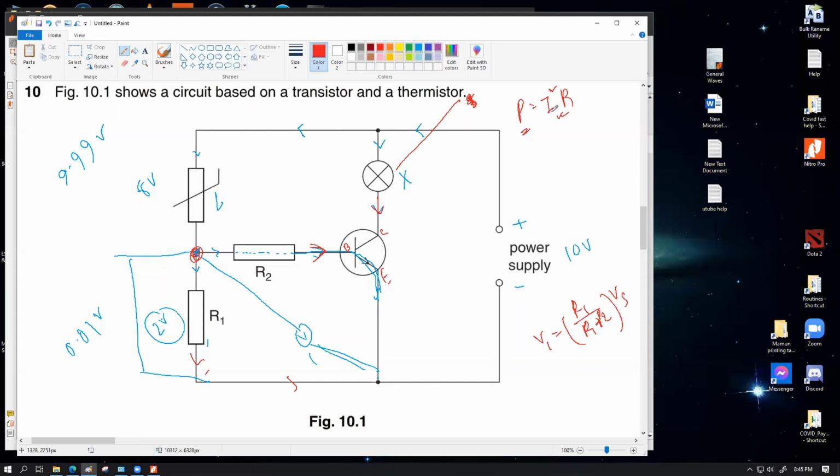So let's say you buy one of those bulbs and take a 1.5 volt battery, or maybe two of those batteries, and then you connect them with the circuit. You would not find that the bulb is glowing. But if you ask, are you not feeding the bulb energy? The answer is yes, we are feeding the bulb enough energy. But that energy is not good enough to light up the bulb. We are having current flow through the circuit. Yes, the batteries are draining, but that amount of power supply is simply not good enough to make the filament start glowing. So whatever heat energy we are producing in that filament bulb is getting dissipated to the atmosphere before the temperature could rise to such a value that it can become glowing hot.